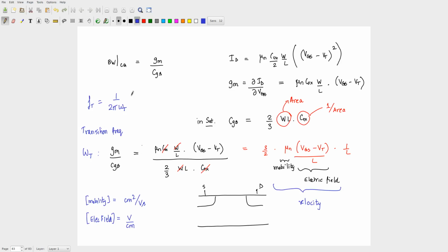So you guys are buying transistors for your experiments for the CAD lab. Go and look at the data sheet for that transistor and find out what the Ft is. It will be interesting. You are buying cheap transistors for doing small work. Ft of that would possibly be in the 10 kilohertz, 100 kilohertz range. Maybe 1 megahertz maximum.